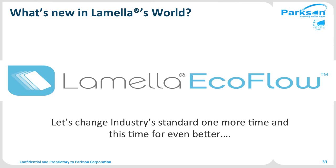So what's new in the Lamella world? For the last 41 years, the industry has been using a design called 80-20 design. Usually the inclined plate settler specification calls for an 80-20 design, which means you can only use 80% of the plate area. The area around the feed slot region cannot be used. So that's why only 80% of the plate area can be used.